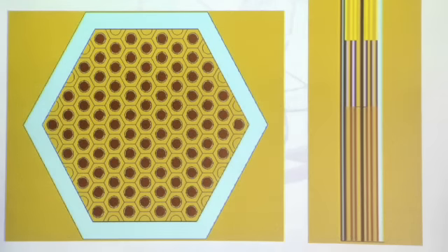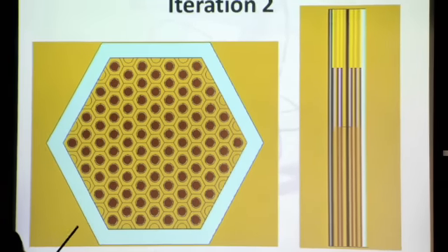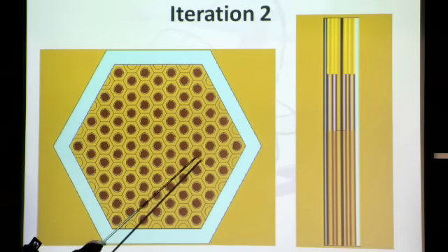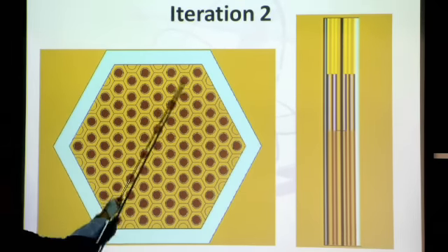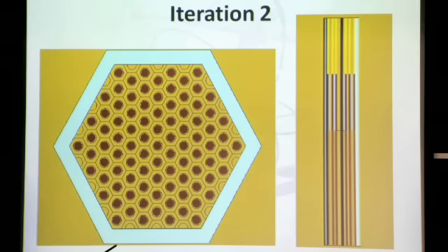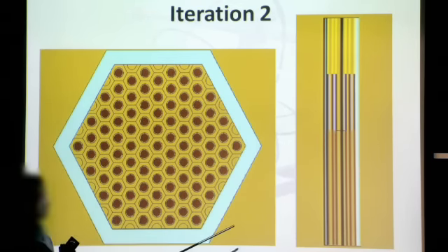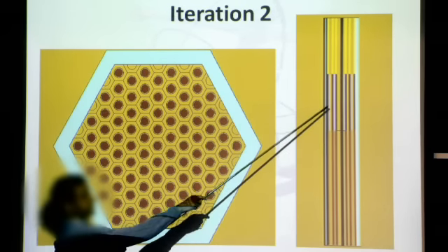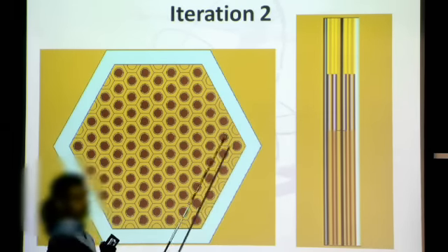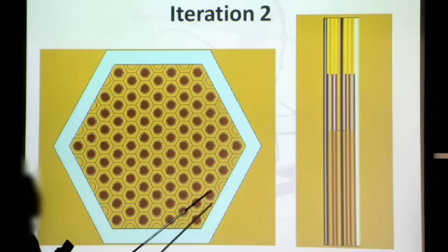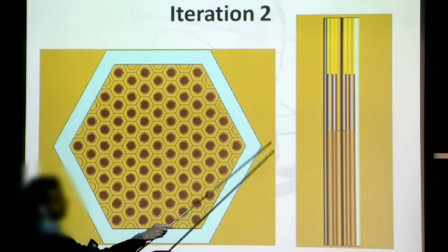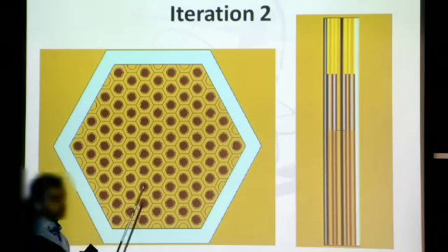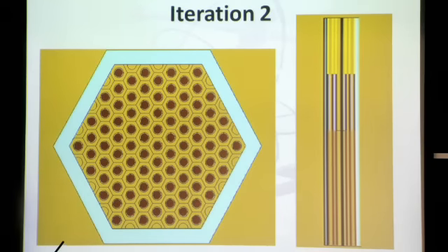Next slide. This is a look at an individual assembly. Again, in the corners here, those lines don't exist. They're just the way MCNP likes you to design universes. And one slight note is that since we made these slides, this isn't 50% and then 25, 25, it's thirds in every region. But you can see how the fuel zone is, each color represents a different type of fuel, and that's how we're zoning.